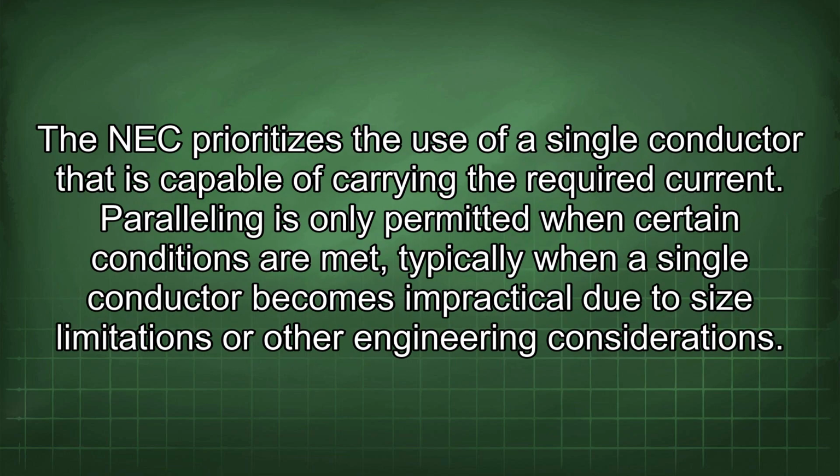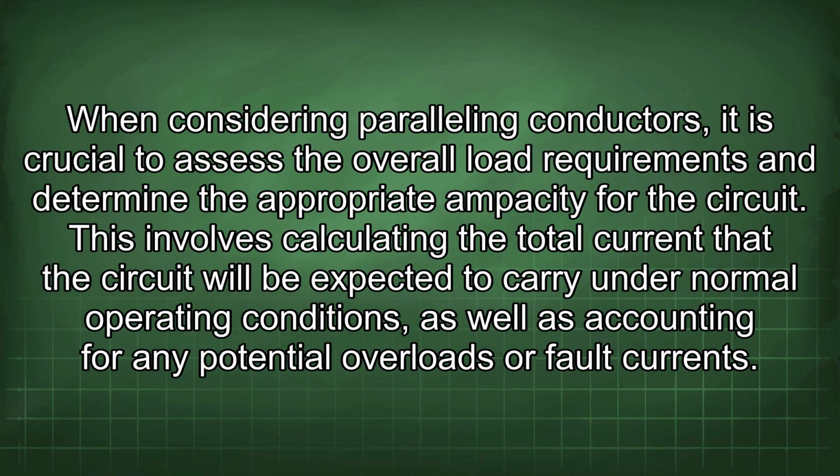The NEC prioritizes the use of a single conductor that is capable of carrying the required current. Paralleling is only permitted when certain conditions are met, typically when a single conductor becomes impractical due to size limitations or other engineering considerations. When considering paralleling conductors, it is crucial to assess the overall load requirements and determine the appropriate ampacity for the circuit.